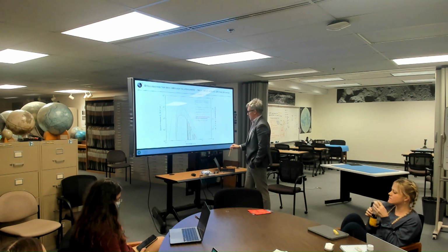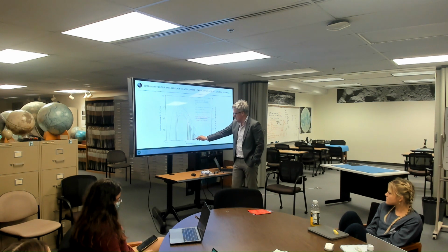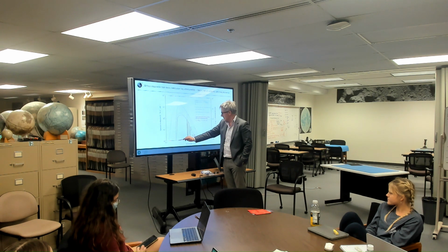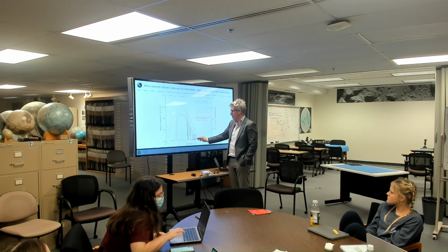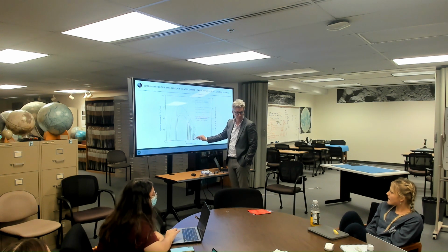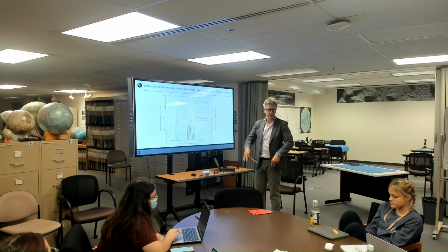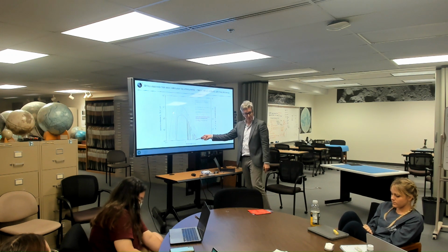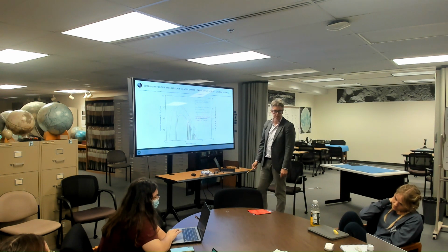If a scientist comes to you and says it's really important I make a measurement right here, that would lead to a very different instrument design than a scientist coming to say I need an instrument that makes a measurement right here. Because here I would be detecting a large number of high energy photons, and here a much lower number of low energy photons. It would also translate into different materials for the glasses and the lenses, and the further out you go, you would have to cool the detector to suppress dark current and thermal effects in the material. We'll talk about that in future classes.